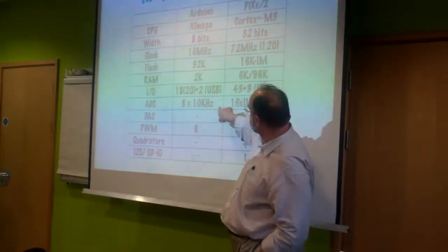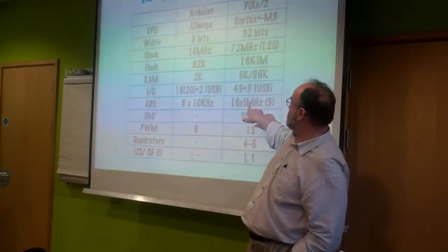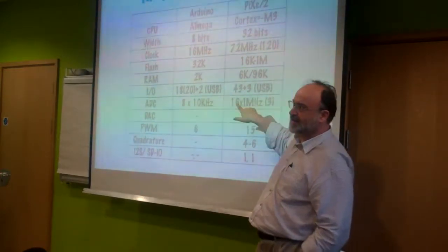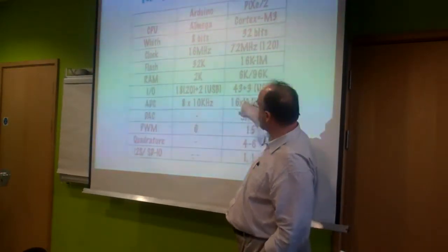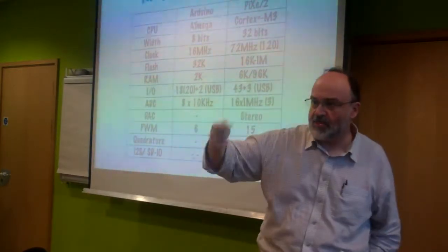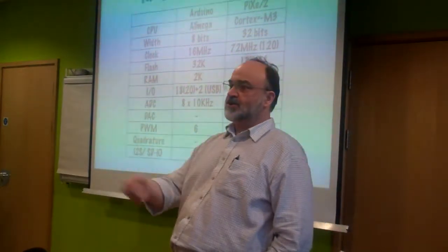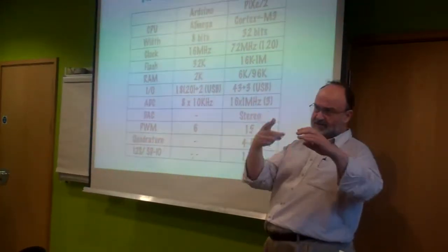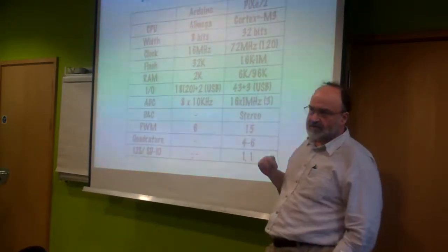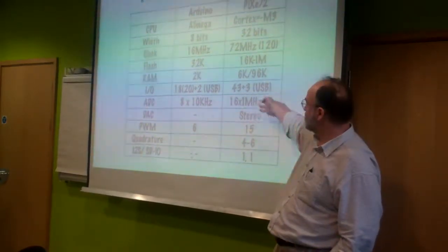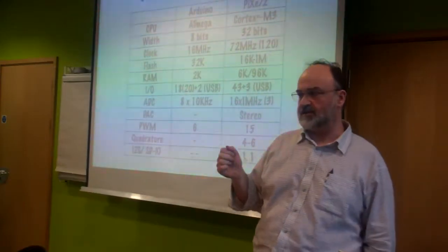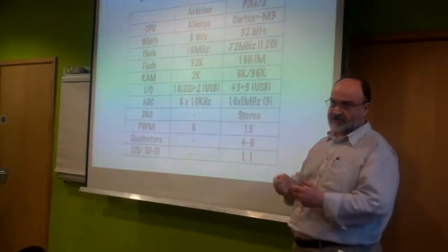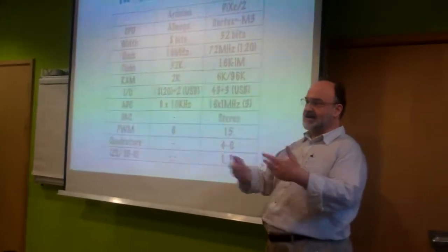So for example, the analog to digital conversion is about 2 orders of magnitude faster, and that's 10-bit and that's 12-bit. If you go and look at theory about sampling systems, you can oversample, and in order to reconstitute or generate, if you inject a little bit of noise, an even higher quality signal. So in theory, you could recover a 16-bit audio signal with that. Plus the highest spec chips have 3 analog to digital converters, so you could actually listen to multiple sound sources.